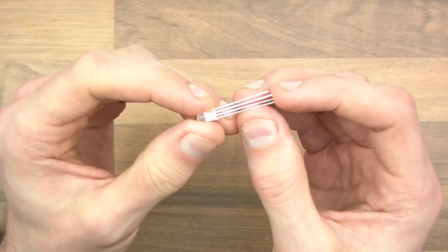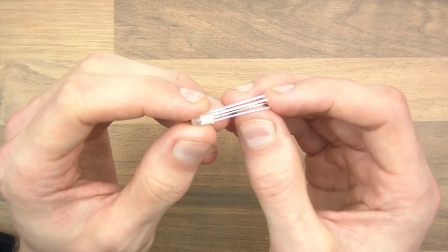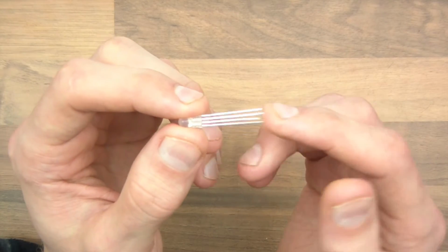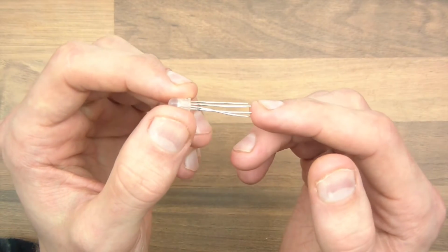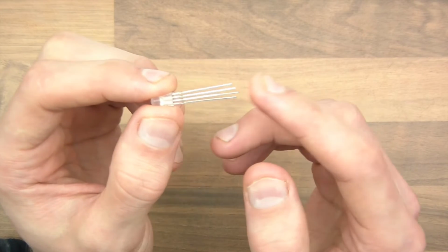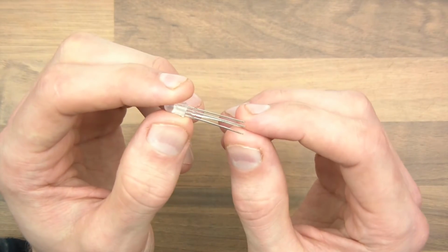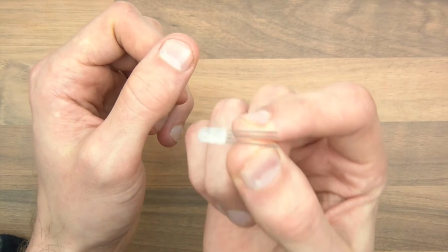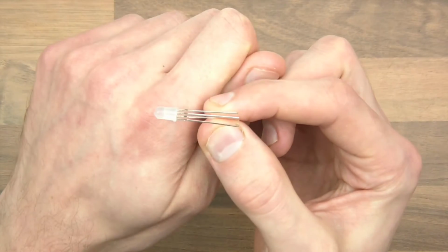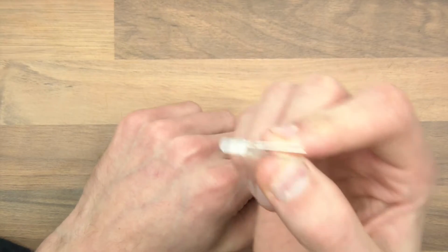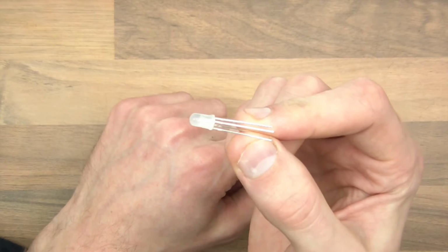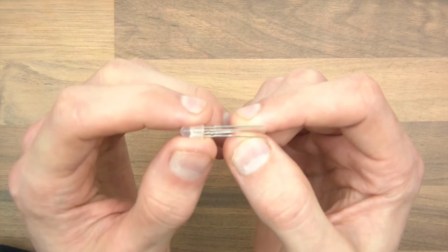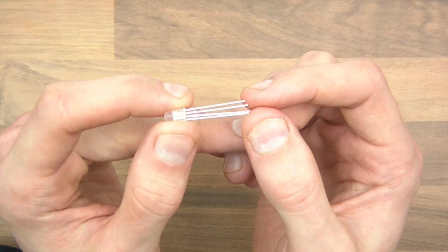And the reason being is because it's only rated for a certain amount of current. If too much current passes through, it burns out. And I suppose it's a bit peculiar, because when beginners start to do experiments with different components, components tend to draw whatever they need and not more, but an LED is not like that. An LED will just draw everything and kill itself. So you need a resistor, a current limiting resistor, and this seems to pose a lot of confusion for new people, and I'm going to explain it, okay?